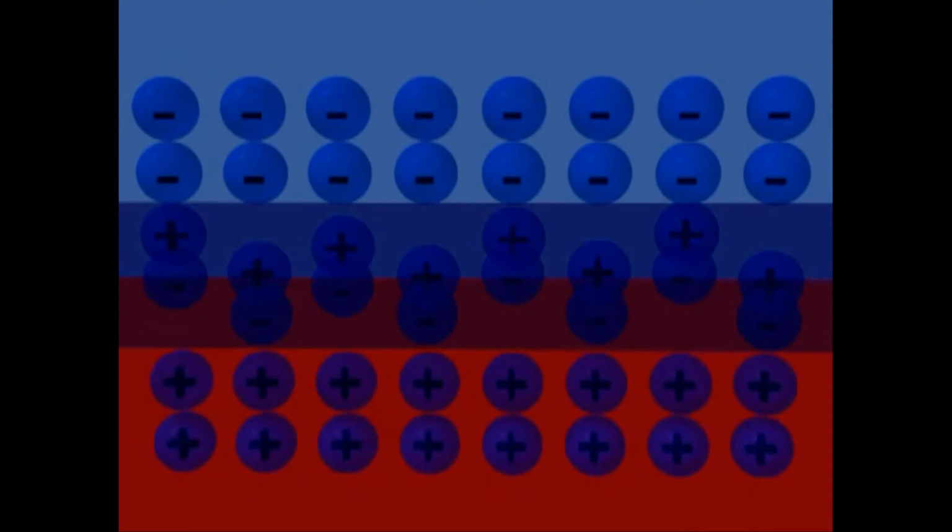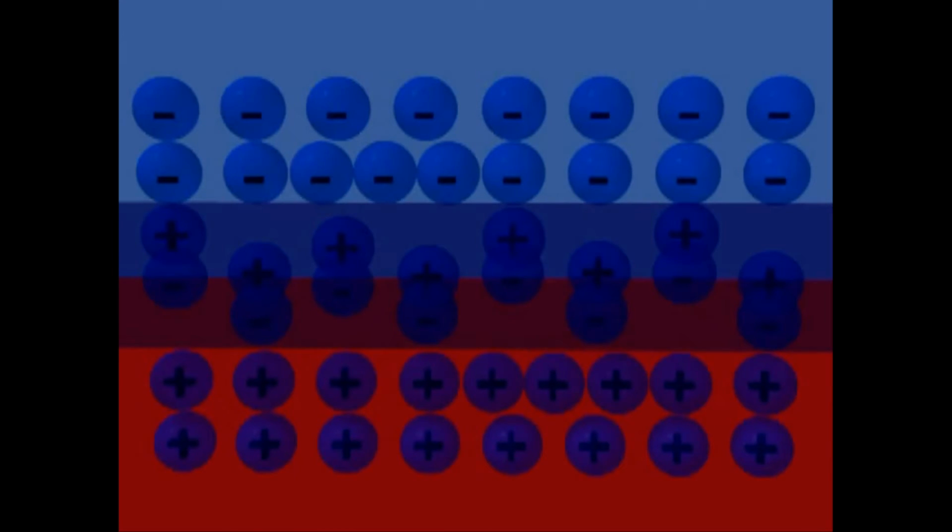Consequently, an internal electrical field builds up at this transition that does not permit electrons and holes to jump into the other layer. However, if photons hit the silicon layers, electron-hole pairs will be created. If this happens in the electrical field, electrons are moved to the N-doped layer and holes are moved to the P-doped layer. The system will fall into a state of imbalance because of an excess of electrons in the N-doped layer. The corresponding holes can be found in the P-doped layer.